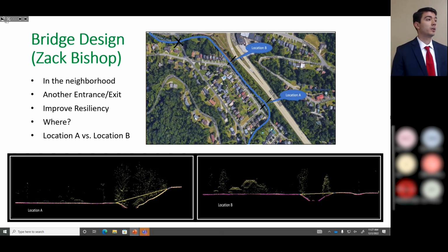So then the question of where are we going to put the bridge? Our first option was location A. We chose this because it has 3 roads connecting into it. This will help funnel people into it to get people quicker and then they can leave to get on Calvary. But once you look at location A's slope, how much the ground elevation changes, it was coming up to a 20% slope the bridge would have to be to leave Enslow and then get on the Calvary. That was not plausible.